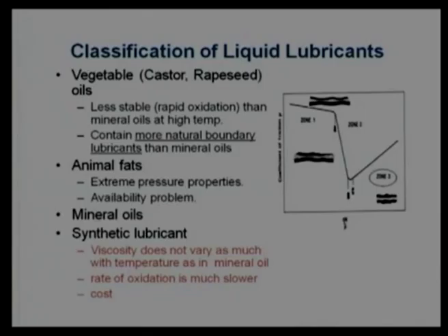Major advantage which is generally quoted is the viscosity. Viscosity degradation is very low. Viscosity index is generally higher than viscosity index of mineral oils. Few synthetic lubricants are slightly costlier compared to mineral oil, which can be utilized for common application. Otherwise, by and large, synthetic lubricants are costlier even 3 to 4 times compared to mineral oil. That is why they have restricted applications and they are used when we do not have any other alternative.